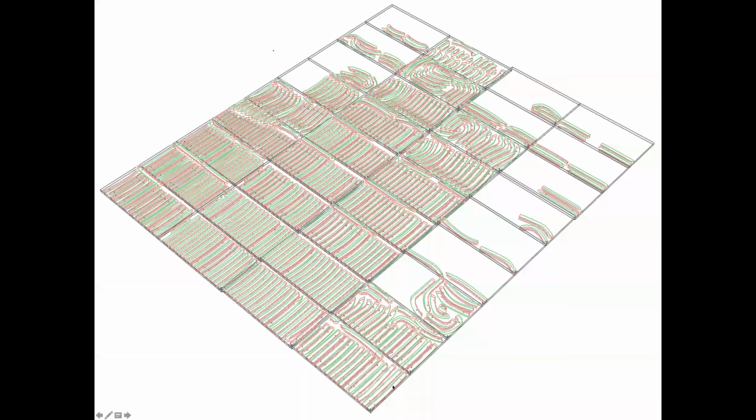In fact, here's a set of 18 by 32 sheets where I took a bunch of two-way structural ribs and nested them to maximize material yield and minimize the waste. Where I do have some offcuts, they're small. I'm still getting a yield of 90% plus. And where I have big spaces, I try to create shapes that I can use later on. The offcuts can be stored and used later, not some really funky shape that is impossible to use with anything else.